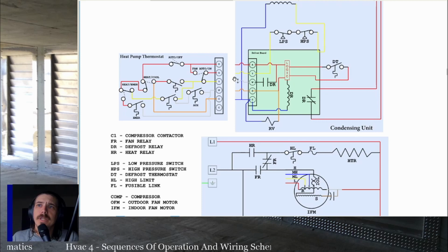We have a cooling thermostat for cooling, a heating thermostat for heating, and then you're going to have an additional thermostat essentially inside of that thermostat, which, once you get far enough away from set point, is going to power the auxiliary or emergency heat if it's not set in emergency heat. So after a particular amount of time or a particular amount of difference from set point, electric heat will come on to bring the temperature closer to set point, and that'll continue until the thermostat reaches set point, and then that process will repeat.